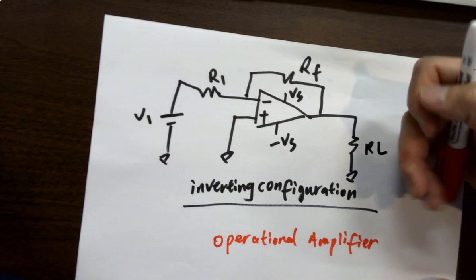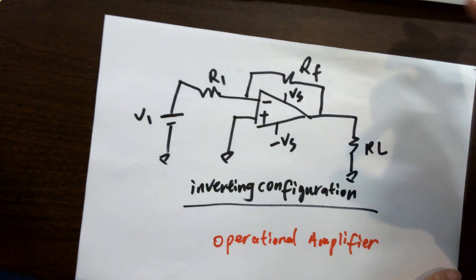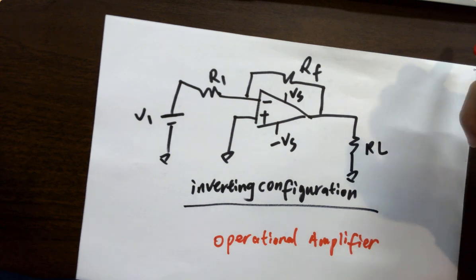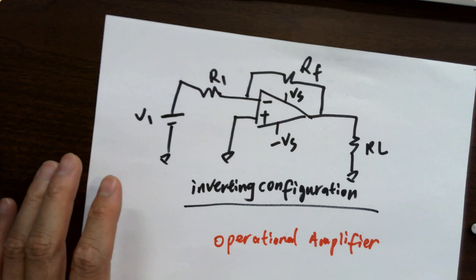So basically it's amplifying signals. It could be a very tiny signal from your heart, like the ECG, electrocardiograph. In the hospital, you see the patient has something connected, usually 3 electrodes, 2 here and 1 on the leg, providing somewhere around 10 millivolts. When there's a heartbeat, it discharges and has all the charges to your skin, and it's using a differential amplifier to collect it. It's usually in the level of millivolts, and that voltage is really tiny and noisy, so you have to use high quality amplifiers to amplify in order to see it.